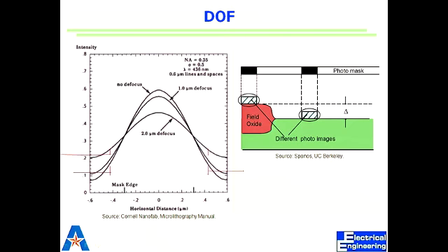And now think about this twist. Right now what we are considering is we are not even touching lambda. Now if you push lambda down as well, this becomes even more prominent. So these are 2-3 equations, and I would want you to know these equations. Remember those equations because they define the relation of light and optics and what we get as feature size. So there will always be a trade-off between lambda, numerical aperture, and feature size. That's why we have to come up with out-of-the-box thinking, which you guys are hopefully doing right now, or not, to solve these things and see what else can be done.